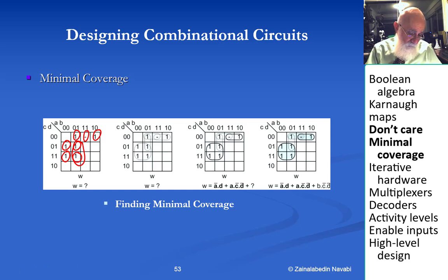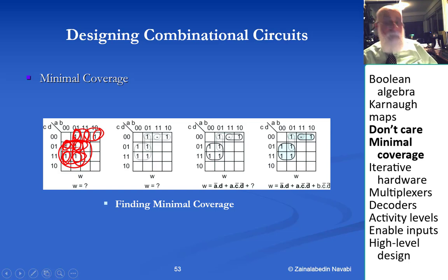So counting 1, 2, 3, 4, 5, 6, 7, 8, 9, 10, 11, 12, 13, 14, 15 implicants. Of all of these, you only have 1, 2, 3, and 4 prime implicants, because there are no other implicants covering these 4 that I have identified.